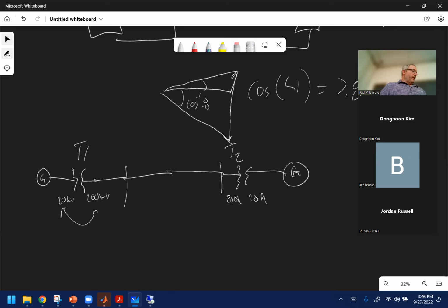The only one that we did on this one is to convert it to per unit. I didn't say do Y bus, I said do per unit. So there's 2 parts. You had an X line equal to 120, so you had to divide that by Z base to convert to per unit. And then my load, as we did in lab, all you took is your S and divided by S base.